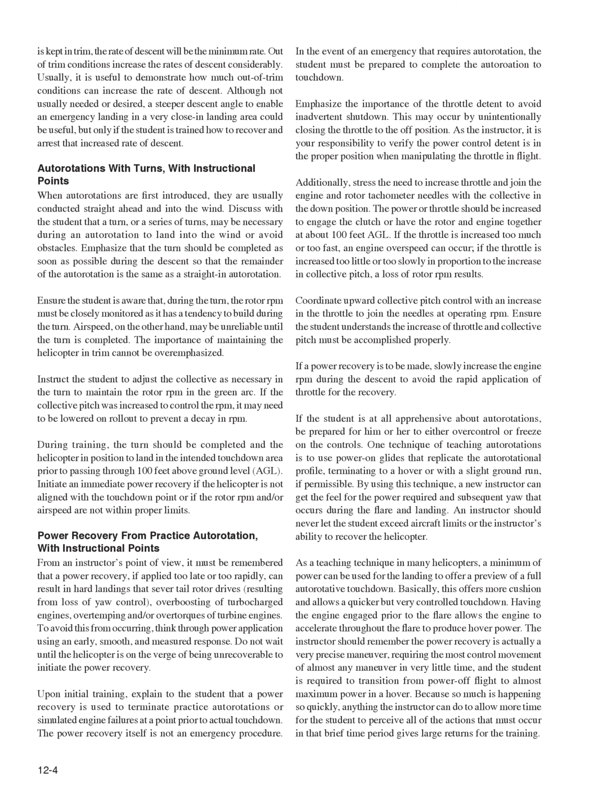During training, the turn should be completed and the helicopter in position to land in the intended touchdown area prior to passing through 100 feet above ground level, AGL. Initiate an immediate power recovery if the helicopter is not aligned with the touchdown point or if the rotor RPM and/or airspeed are not within proper limits.